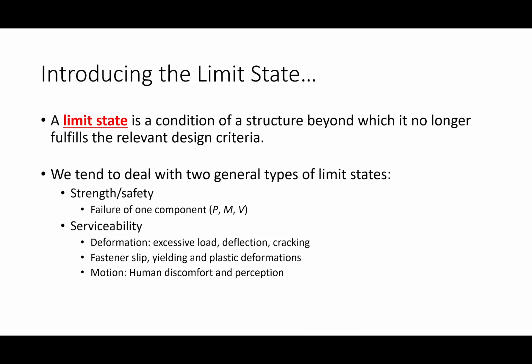Tension members are when you take a piece of steel and you yank on it, okay? A limit state is basically asking what are the different ways that that tension member can fail? Or more specifically, what are the conditions that we can define for that tension member such that should those conditions be exceeded, we're going to consider the member not in compliance?